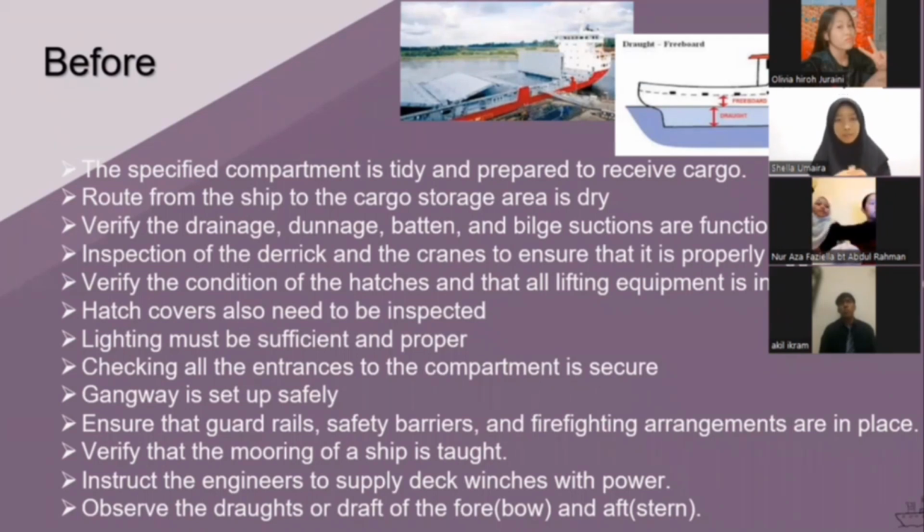The place needs to be always dry, or if there's a slippery place, you need to put some signage to make sure the employees are aware of the environment. Then verify the drainage, pumps, and bilge sections are functioning properly, and inspect the derricks and cranes to ensure they are properly rigged.